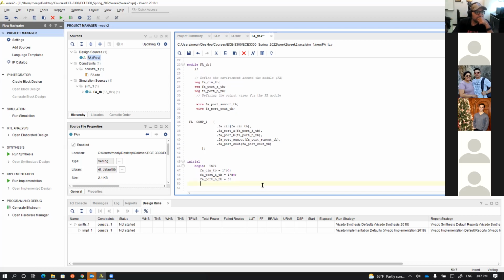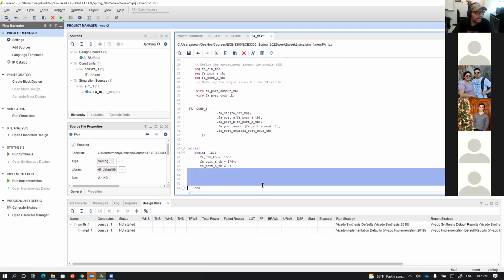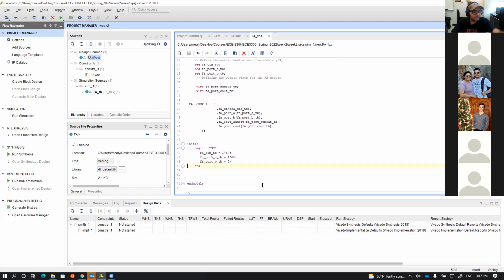If I don't add anything else than that, if I run the simulation and look at the waveform generated out of the test bench, those will be zeros forever. But this is not the right thing, because I would like to see what happens if I change cases. Do you agree?